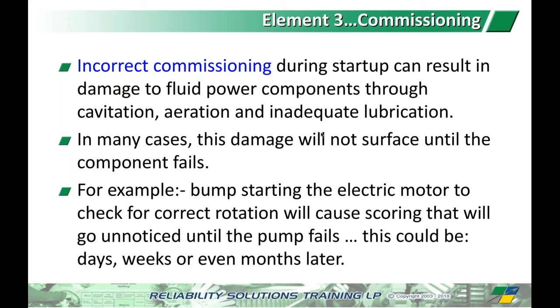Heck, you can even get it on Amazon now. You get yourself a phase rotation meter. You don't need to bump the motor. You can check for phase rotation ahead of time, make sure the motor is going to be running in the correct direction. But anytime we starve it, anytime we put air into the system,